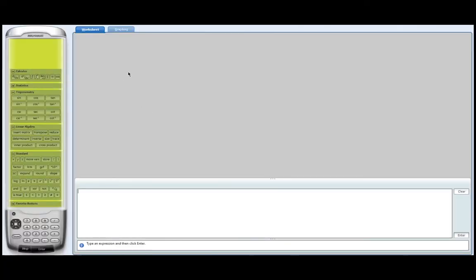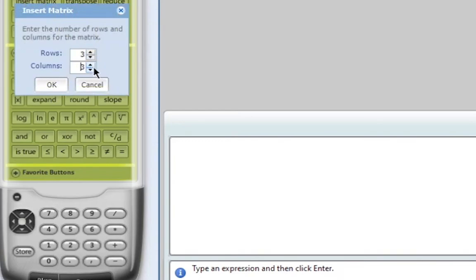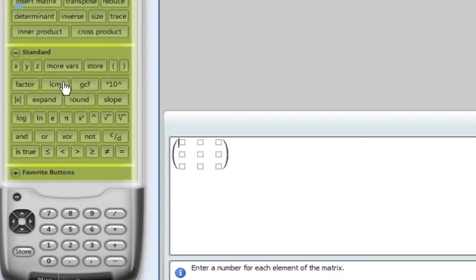Okay, so this is MS Math 4. This is what it looks like, and let's try to compute the eigenvalue of the stress tensor that we are given. In the left corner, you have the linear algebra section. Let's first insert a matrix, so we are inserting a 3 by 3 matrix. Our 3 by 3 matrix, our Cauchy stress tensor, had in the x direction 75 tensile stress.